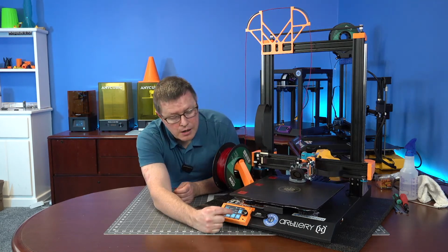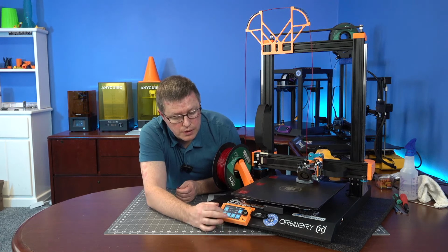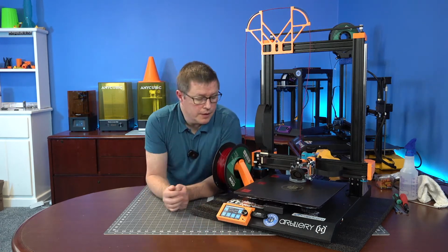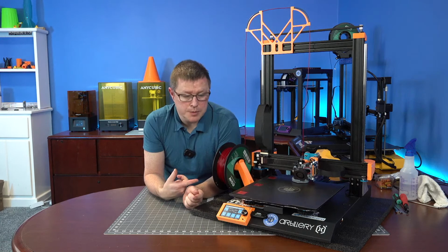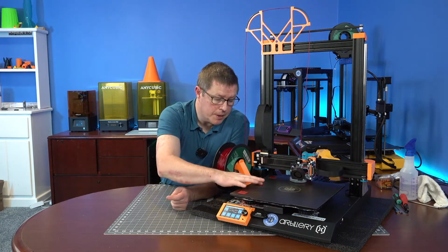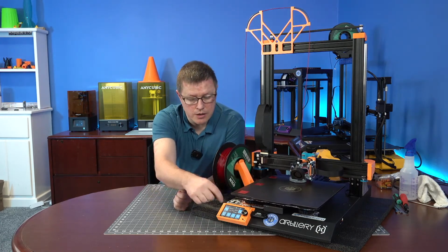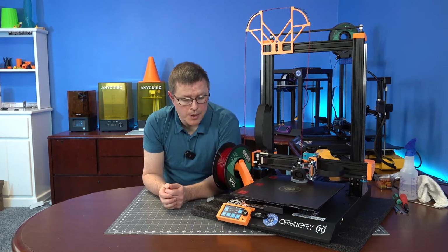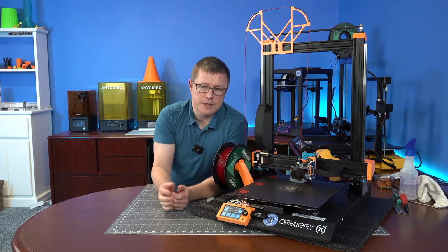Still just a hair too low. And that's the joy of doing this print, because after each one is done, you can look at it and be like, oh, that was way too low or way too high, and you could, you know, baby step away, and it saves it to your nozzle offset.